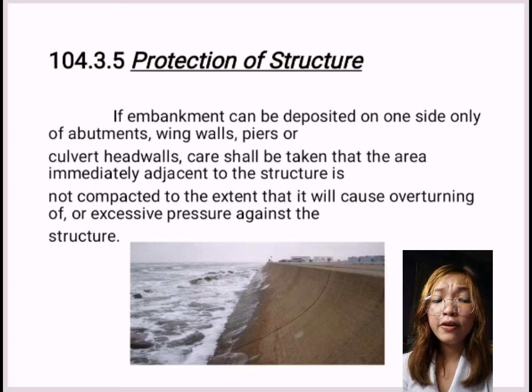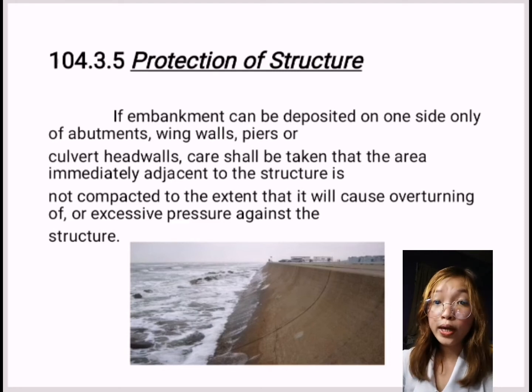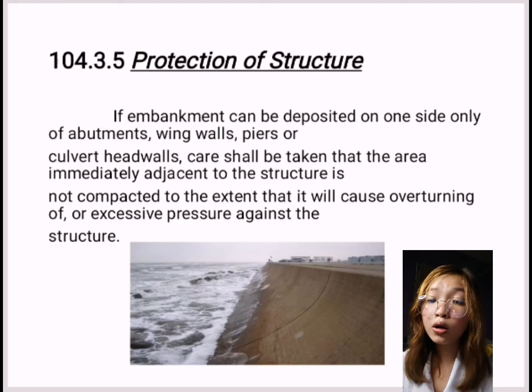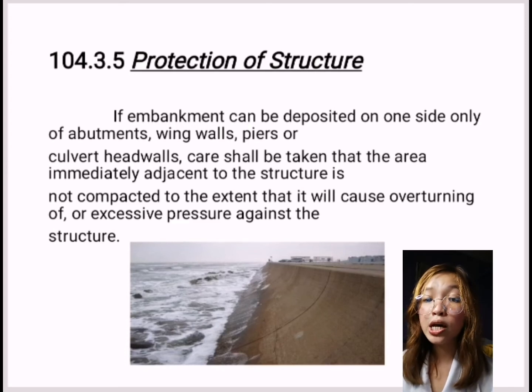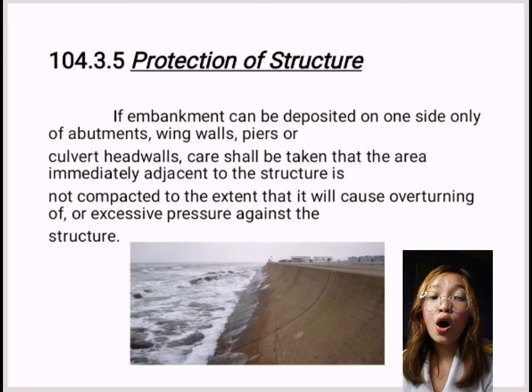So if embankment can be deposited on one side only of abutments, wing walls, piers, or culverts, head walls, care shall be taken that the area immediately adjacent to the structure is not compacted to the extent that it will cause overturning of or excessive pressure against the structure.